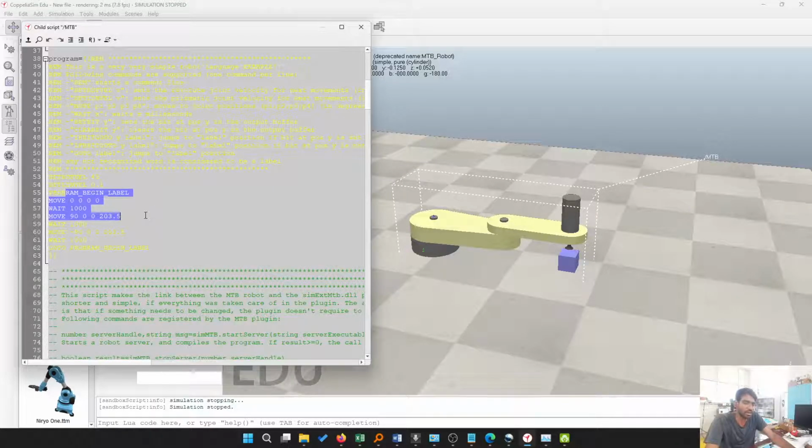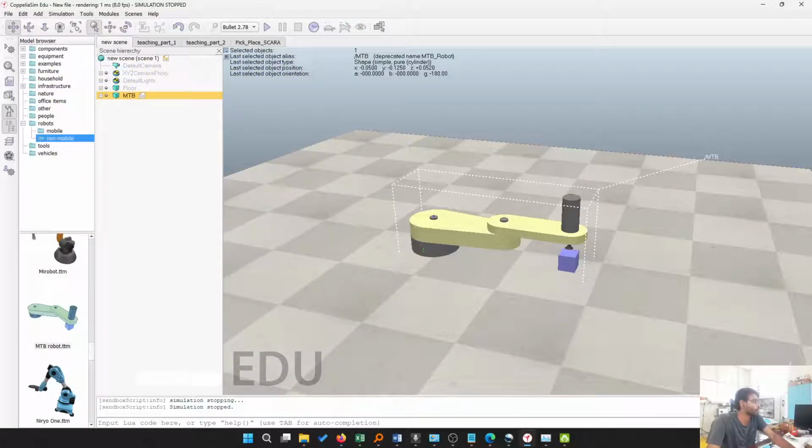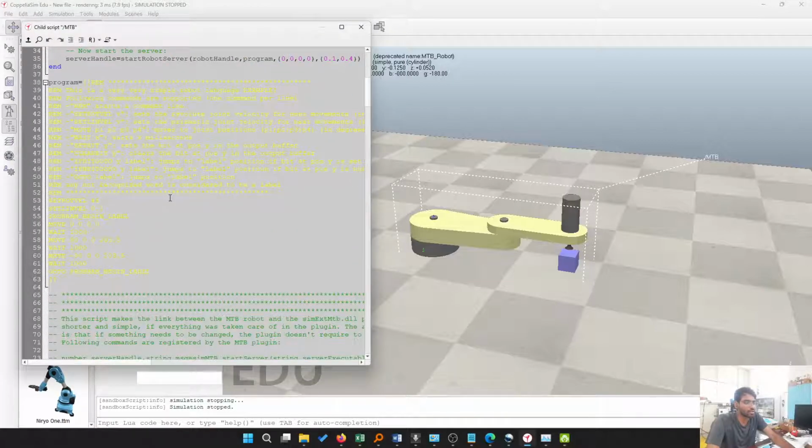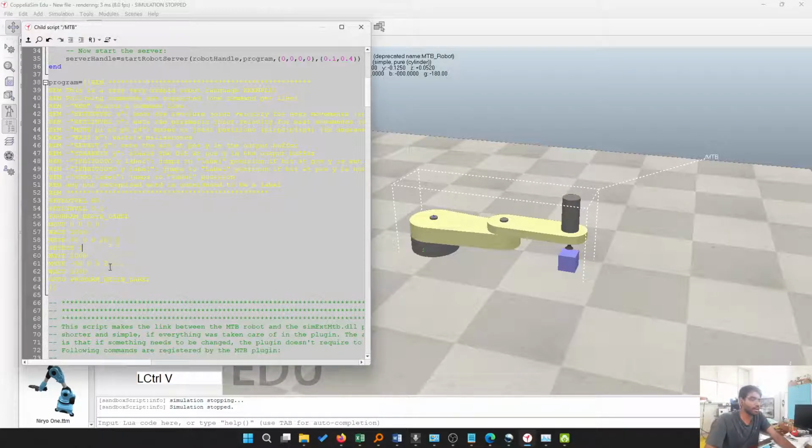Next is how do we tell the robot, when this block is there? Let's say there will be a proximity sensor, and that proximity sensor will tell, okay, now the block is here, then only you go and pick. I also have to tell you how to pick and place. There's something called set. If you go back, you use a command called set bit and clear bit, and that will basically enable and disable the gripper. This is a vacuum gripper. So you have to use a set bit and a clear bit.